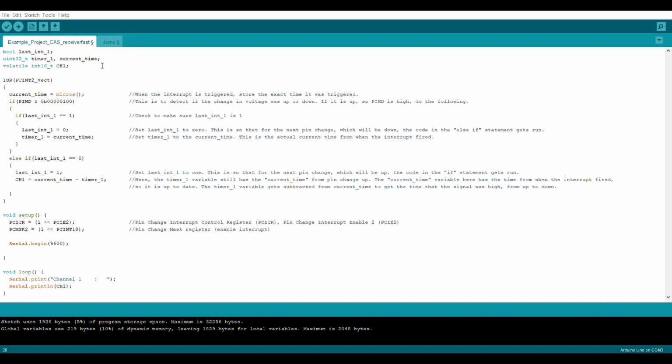The nice thing about this piece of code is it can be expanded to basically all of the Arduino pins. Of course, then you get weird timing issues where if you have an interrupt at the same time on a single bank, then you might miss a couple of interrupts, but that doesn't really happen with this setup.